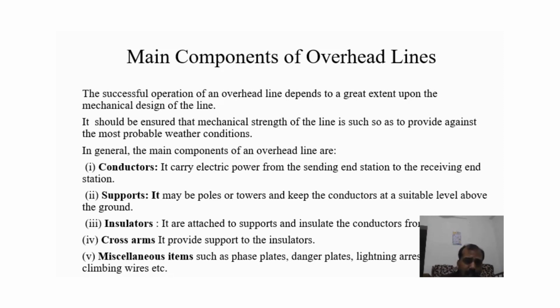Third is the insulator. We cannot directly connect the conductor to the supports, because to insulate the conductor from the support we require insulators. So the insulator is attached to the supports and is used to insulate the conductor and supports.